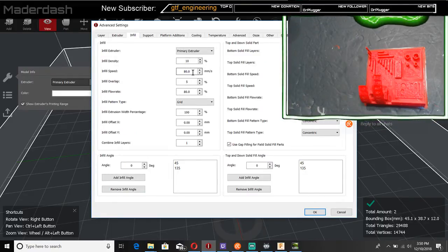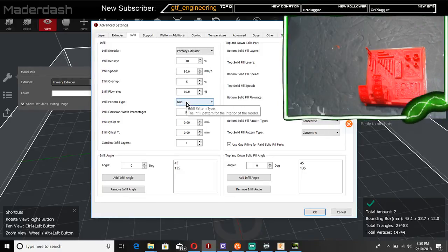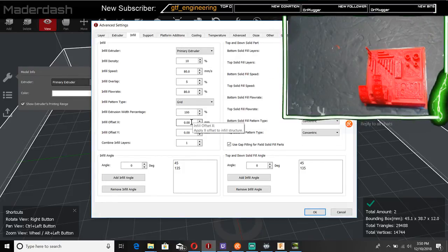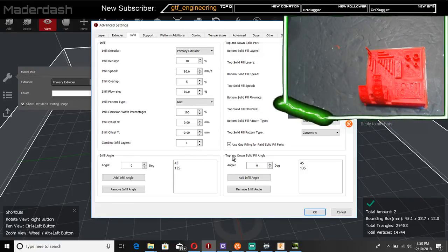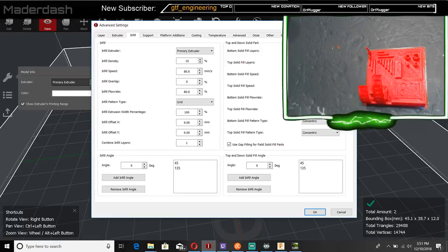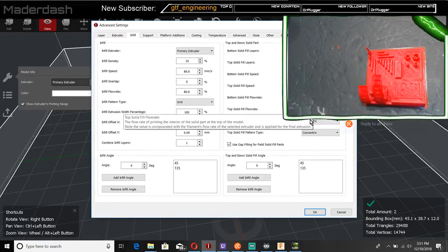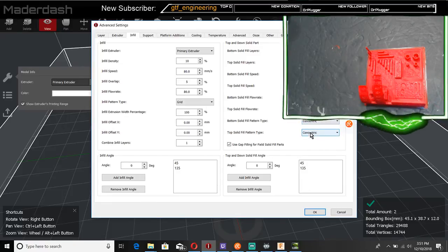Infill, 10%. We'll use a grid. I want to change the grid size though. So where's grid size? Infill offset. 3 solid fill layers on the bottom, top. We can go ahead and speed this up to 50. 50. Concentric, yes.